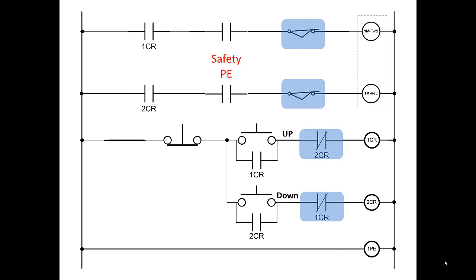However, what happens if, say, a little kid walks through the beam that stops, but then he turns around and stands there and straddles the beam with his legs? It's going to come right on down and pop him on the head. So, in industrial circuits, you're not allowed to have any what's called unexpected motion.